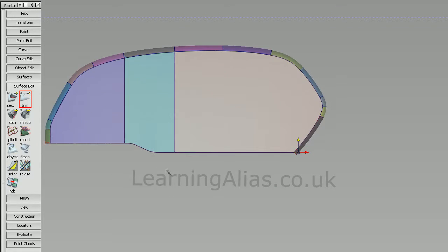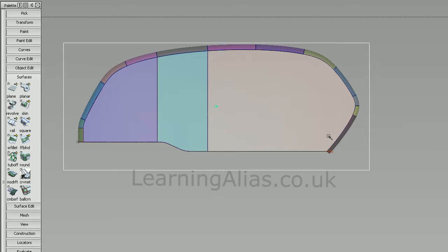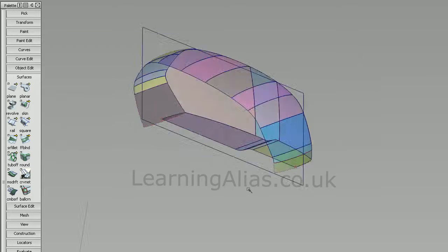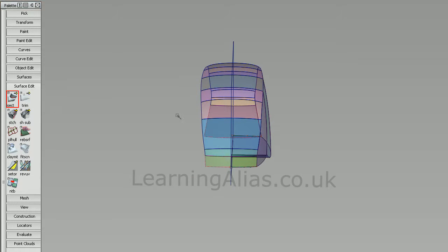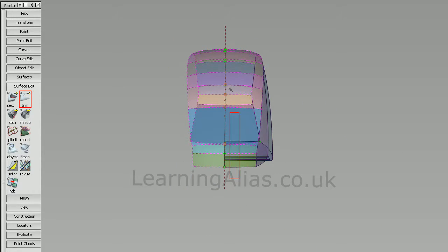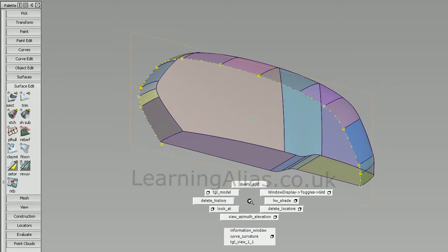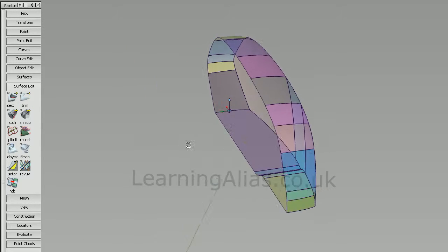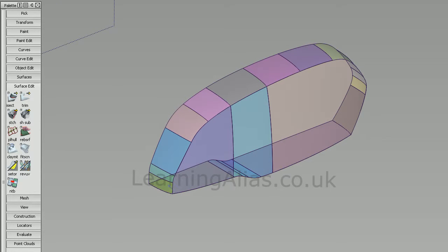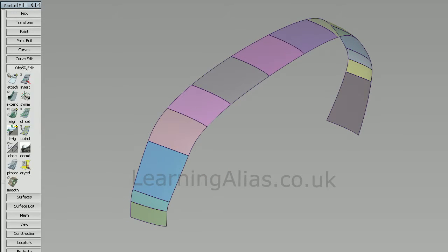Now we just got to do the top surfaces, so put a plane down in side view and you can see that it's intersecting all of our top surfaces. So use the intersect tool and then the trim tool, drag select, keep, and there you are, top surface is trimmed. Then we just hide that or assign it to an invisible layer. And we've created the outer volume of our tank. We can now move on to building the blends between the top and side surfaces.